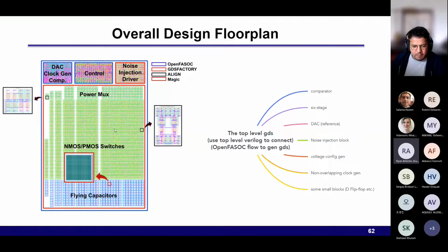Do you think GDS is actually a way of managing this, or would you prefer something else? I think GDS is not great for doing this, right? You still need connectivity. LEF/DEF is kind of in the middle, but it doesn't have the front end of line layers. So something in between would be great. But I think if you combine the GDS and LEF/DEF, or some kind of SPICE LEF/DEF type of thing, that would be helpful.